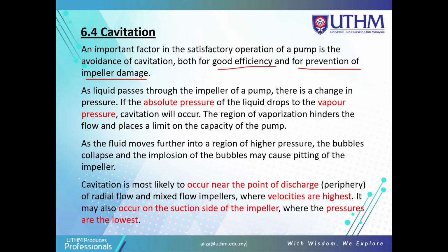So as liquid passes through the impeller of a pump, there is a change in pressure. If the absolute pressure of the liquid drops to the vapor pressure, cavitation will occur. The region of vaporization hinders the flow and places a limit on the capacity of the pump.